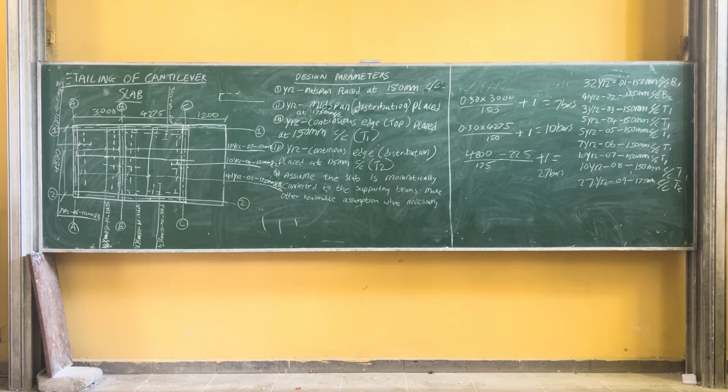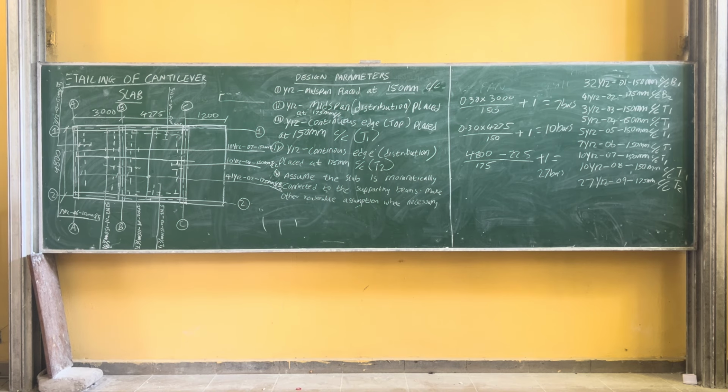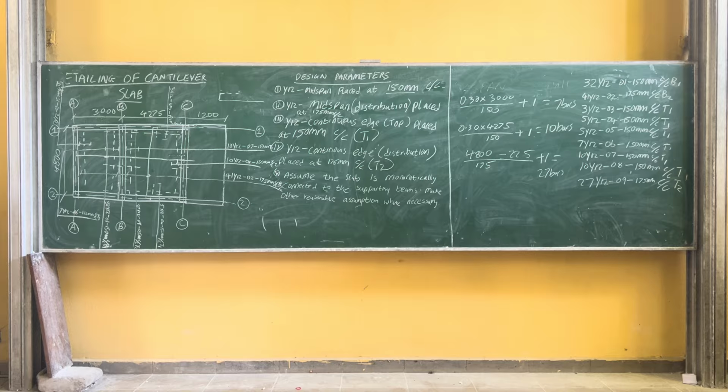A normal cantilever has a fixed end. When there's a force acting on it, it will bend, it will have a hogging moment, which is this top. So we are going to place a reinforcement at the top bar to prevent it from hogging. Normally, for a normal supported slab, if you place a force at the middle part, it will deflect. But this one, the cantilever is hogging at the top. So our main concern is placing a reinforcement at the top here.